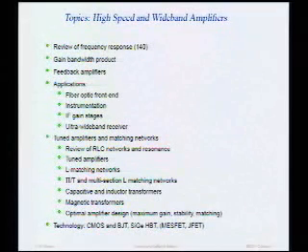Now, silicon germanium bipolar is a lot like standard bipolar that you guys know and hopefully love, but silicon germanium transistors are actually HBTs. They're heterojunction bipolar transistors, which means that from your perspective, the small signal model looks the same. The only difference is that RB is smaller and FT is higher, so it's nicer.